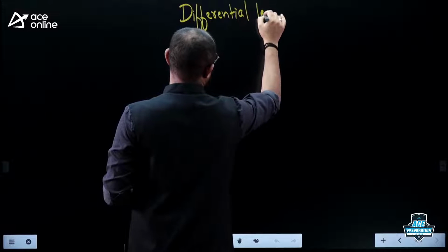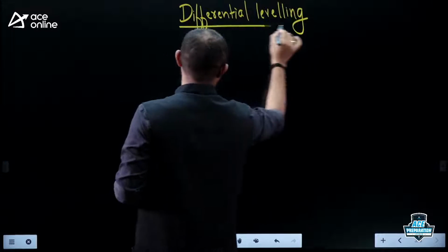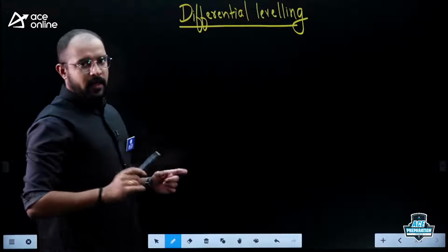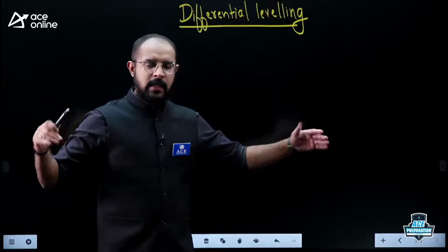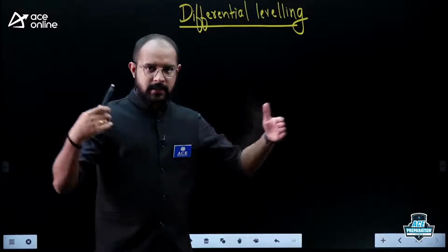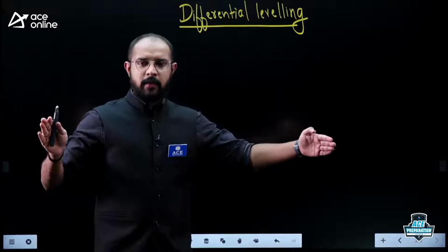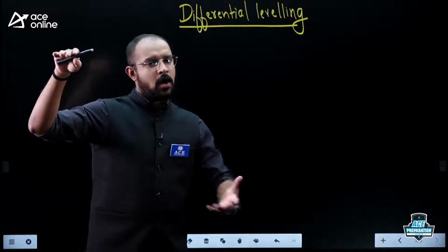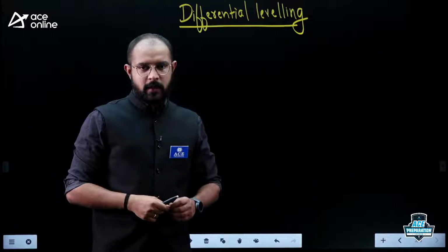What do you mean by differential leveling? Rather, when will I go for differential leveling? I will go for differential leveling when the distances between the points under consideration are very large, the difference in elevations between the points is very large, or when there is an obstacle present between the two points. Say I have point A and point B: if they are very far apart, the difference in elevations is large, or there is an obstacle between A and B, I will go for differential leveling.